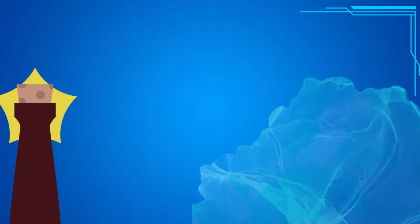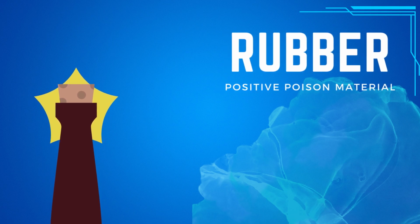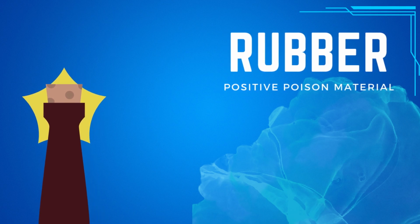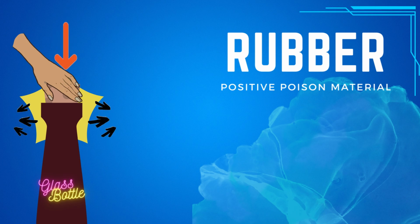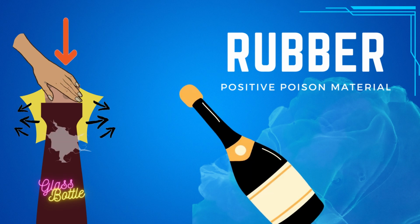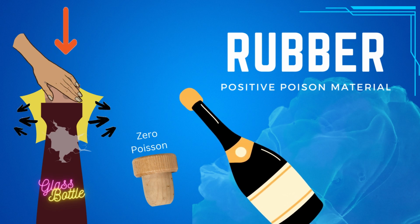Okay, so let's take an example of a rubber cork. Rubber is a positive Poisson material and you are using it to close a glass bottle. When you try to push the cork from upwards, the cork will have a lateral strain and expand, thereby applying a force on the glass bottle, which may be the reason to break it. But on the other hand, the wooden cork, a 0 Poisson material, will not exert any lateral strain to the glass bottle, thereby it saves it from damages.